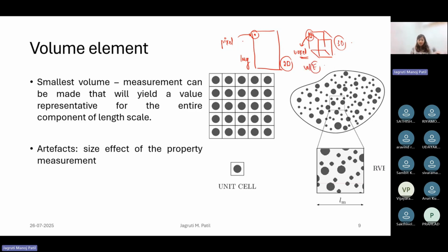And when you characterize your entire material using this one specific, smaller volume element, you assume that this element will have information about the whole material. So here, you have a homogeneous box placed around, with multiple unit cells next to it. Assume this is my structure that I'm trying to image. From this structure, I'm taking this specific volume element and characterizing it. This is the length of the grid, or my scaling length. So from this particular unit cell, I'll be able to make interpretations about the material or sample that I have over here.